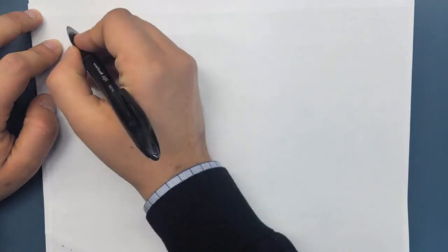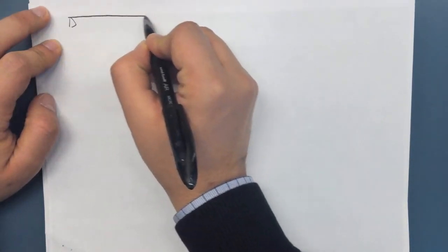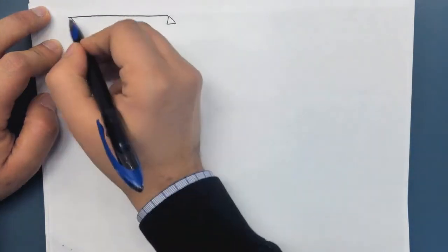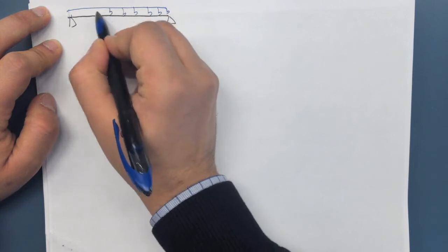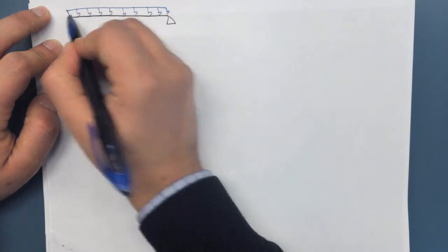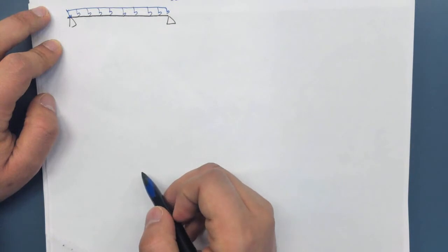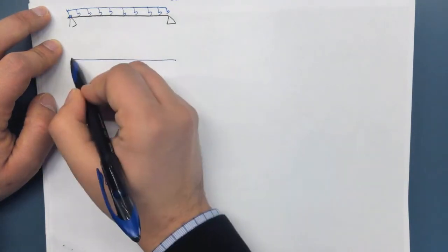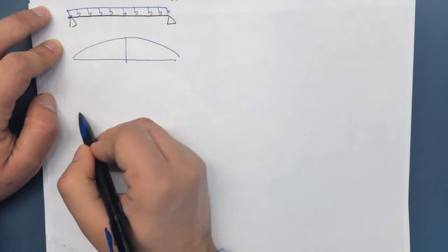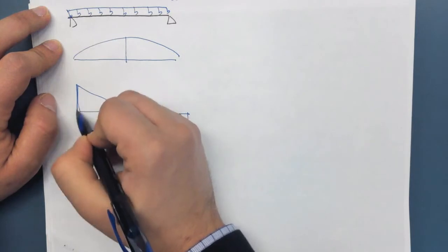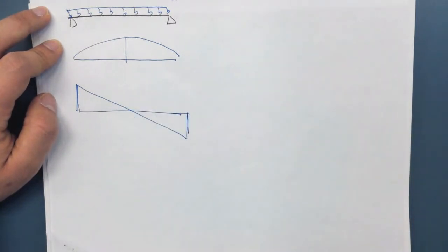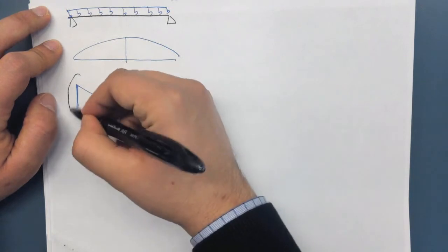So what's happening here is, if you look at a beam, and on this beam there is a uniform load, W. Now, if you recall, the bending moment looks something like this, and this is what we design for, and the shear force looks something like this. So we have a shear force distribution where this is the shear that we design for. We want the section to carry this shear here and here.